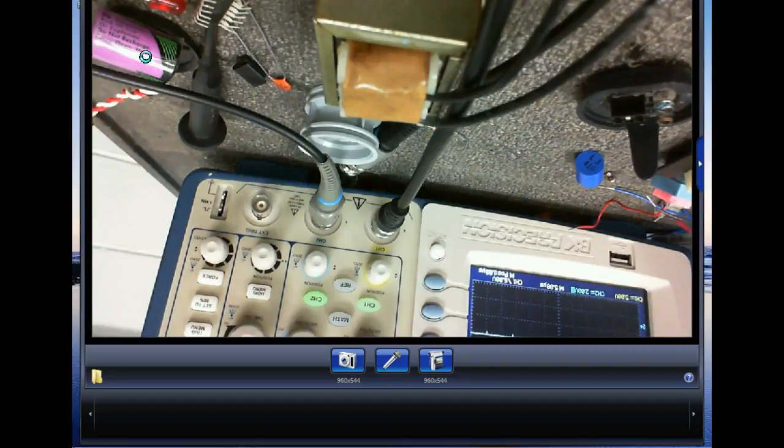You can't just measure it. So if you go over there on the output, you measure V times I on the AC circuit, you calculate what's called apparent power. You wouldn't know what the real power was unless you could measure that ratio. You call it power factor.